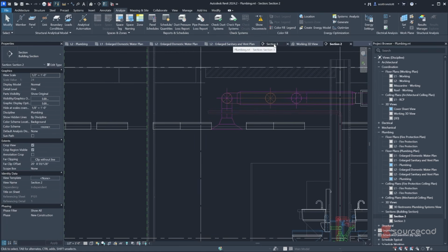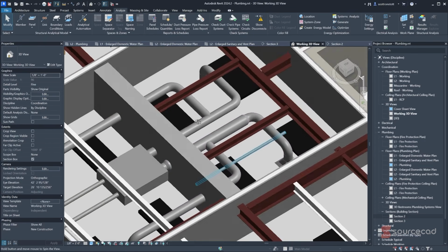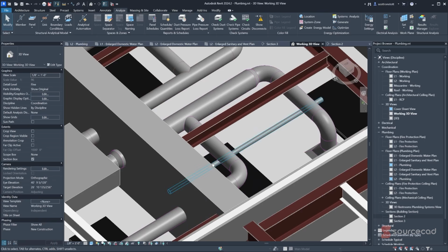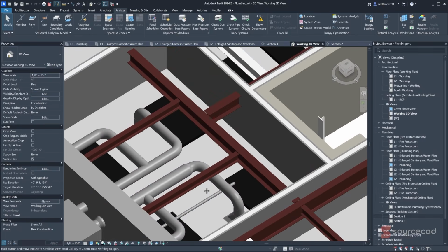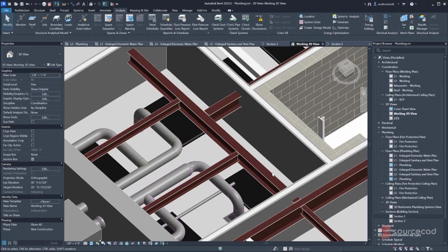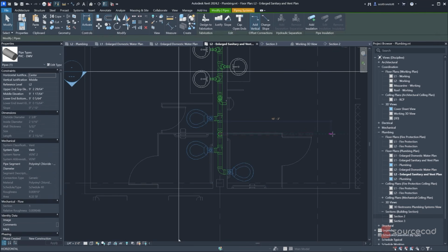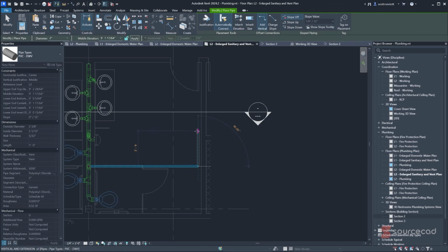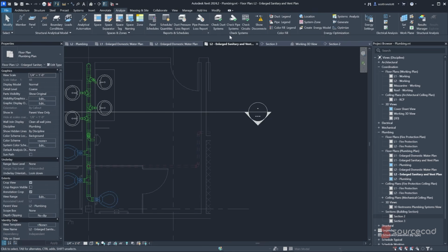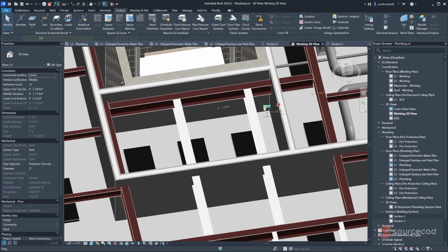Let's take a look in 3D again, see what's happening. Here's this pipe that I'm drawing right here. Just need to make sure that it's not running through a duct or a light fixture or steel. And we'll do an interference check in a moment after we route this to see how that's working out for us. But I'll go back here and draw this over further and then draw a pipe out of there. You can rest assured that you're in the same plane if you draw it off of the end of an existing pipe. Yeah, so here, I'm able to see that right there.